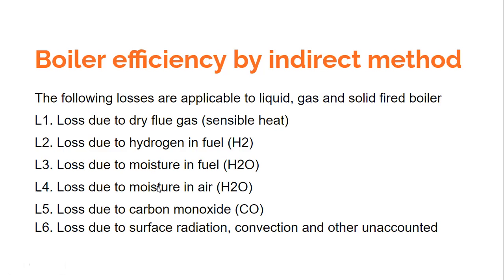Again, if the climate is humid, it means that there is moisture in the air, and if you compare it with a situation where you are operating the boiler in a dry climate, you would find that the loss is more when you are operating that boiler in the humid climate. And why is that so? Because there is moisture in the air which has to be evaporated, and that could consume certain energy from the fuel which is being supplied. Okay, so there is loss due to moisture in the air.